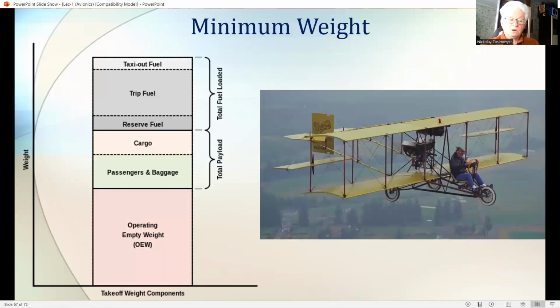There is a great effect from unnecessary weight, which is of the order of 10 to 1. For example, a weight saving of 10 kilos enables an increase in the payload capability of the order of 100 kilos. The effect of additional weight is a vicious circle.